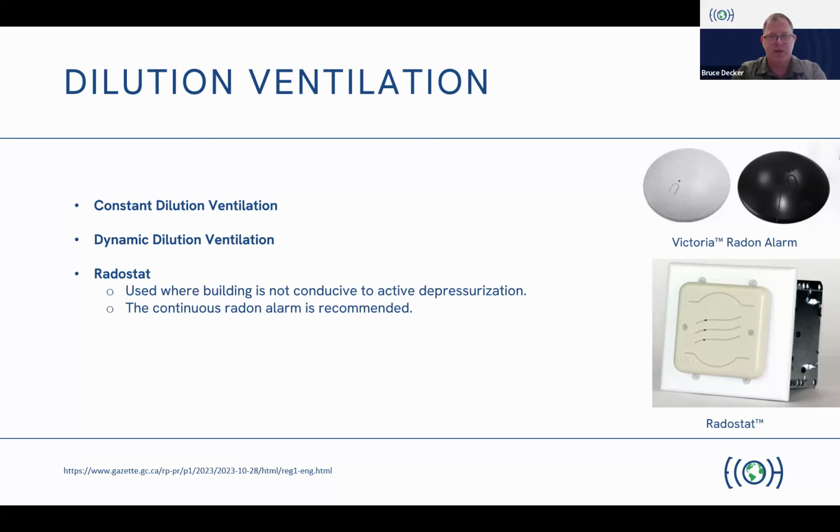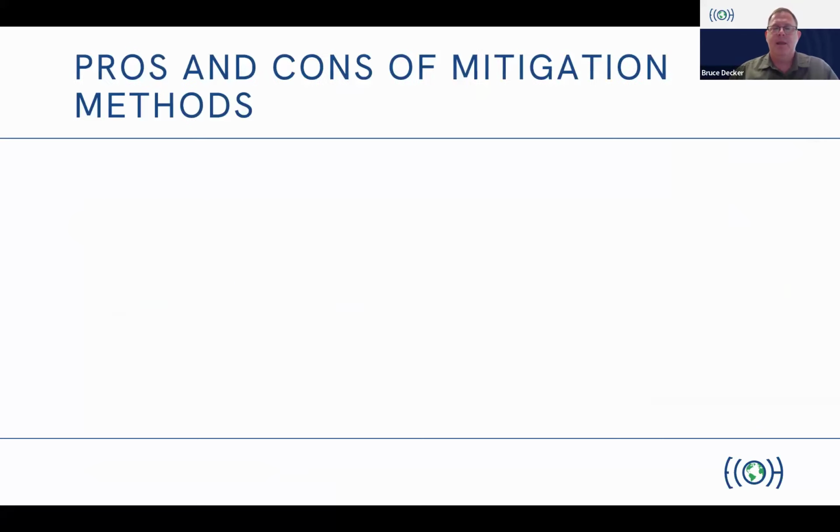And this meter is apparently smart, so it can view trends and optimize its energy over the time period, but you're still pulling in a lot of fresh air. You haven't solved the radon getting into the building. Your solution to your pollution is dilution, right? So there's pros and cons to all these, right?